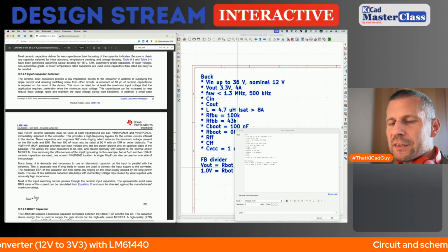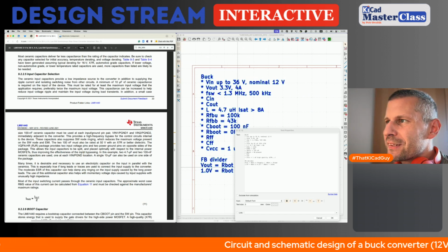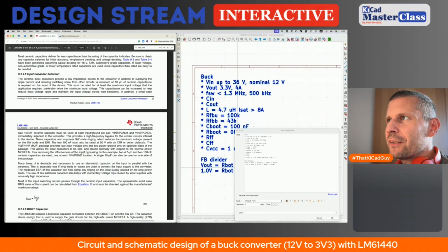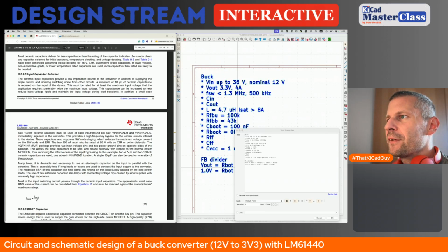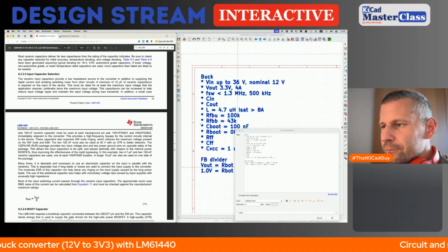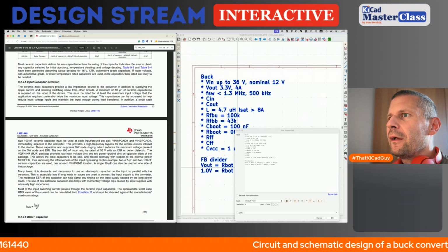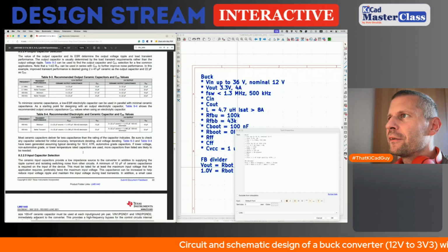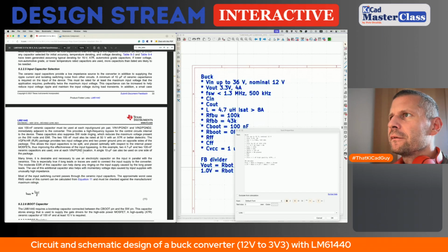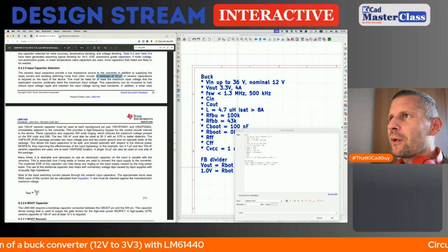Again, the MLCC datasheets usually don't say anything about the input currents or maximum currents. So again, we will use a battery of multiple capacitors. Their recommendation is a minimum of 10 microfarad of ceramic capacitance.